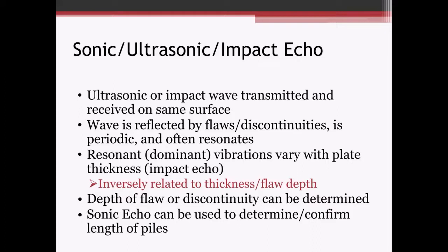That wave reflection is periodic, and it often resonates at some dominant frequency, and that dominant frequency varies with the thickness. As your thickness increases, your frequency decreases, so it's inversely related to the thickness or the flaw depth, if you're looking for flaws, discontinuities, delaminations, voids, or something like that.